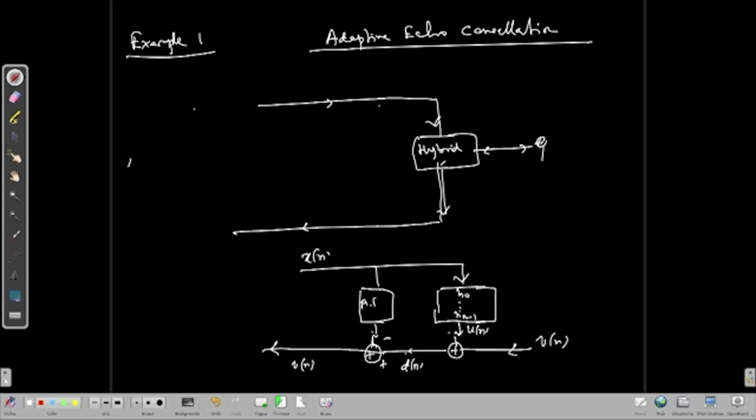So, adaptive filter, AF. What it does is, the filter output Dn minus the filter output, this and this Xn, these are used in adaptation. Adapt. The filter output Dn minus this is the error. So En is given to the adaptive filter, Xn is given, and it changes the coefficients like this.